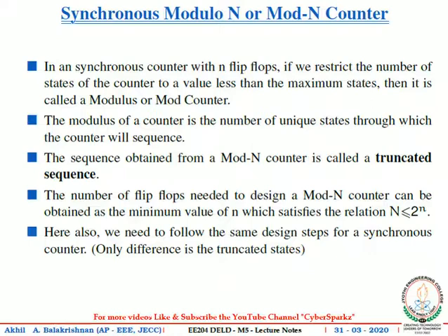The design procedure for a modulo n or mod n counter is the same as that of a synchronous counter. We have to follow the exact steps. The only difference is that here, as the number of states is less, the invalid states we need to treat as don't cares at the time of designing.